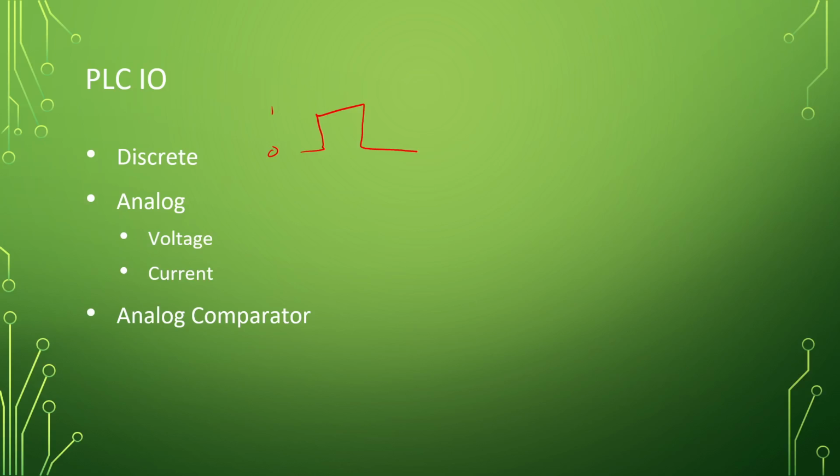We invented things that are soft starters, so when you would do that, it would slowly put half power in the motor instead of full power, so it would start spinning slower, and then you would go to full power, so it was like a 2-stage or maybe a 3-stage system. But that's still just a discrete, turn the motor on type of thing, and it works just fine. So discrete really gets a lot of things done. Turns lights on, can turn conveyors on, heaters, those types of things. But if you start needing true, nice control of things, then analog is where we start heading into.